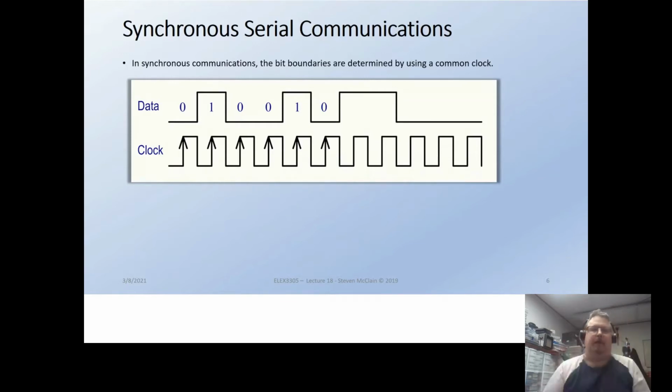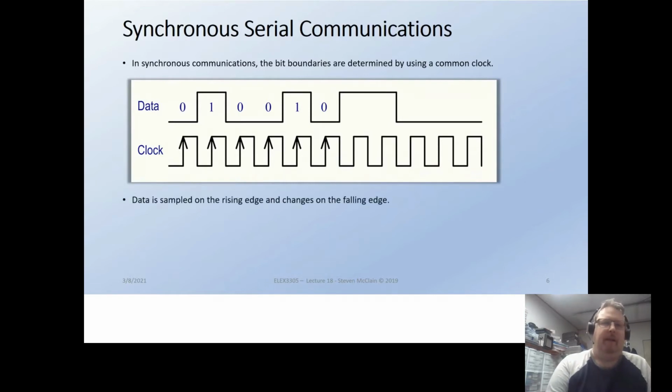and that'll just take a little snapshot and say, okay, you're a 0. Decided today that that one's going to be a 0, and then this next one's also going to be a 0. And then, oh, it's a 1 now. Okay, well, now it's a 0. So that's basically the general idea of serial communication: sampled on the rising edge, changes on the falling. And of course, you can flip things and make them opposites, and it's always the potential to be opposite day in CPU world.